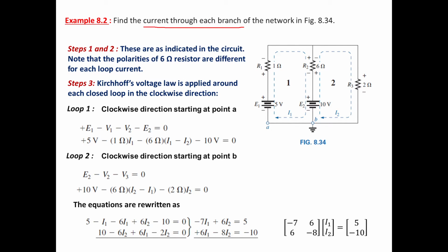So what is the first step? The first step is to identify the window. Here there are two windows. After you identify the window, assume the current in clockwise direction. So this is I1 and I2.